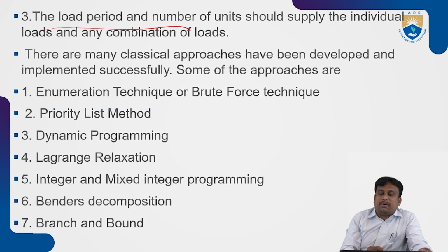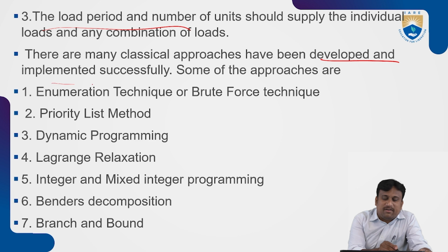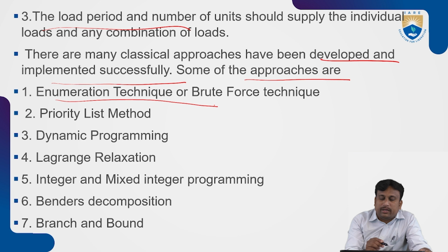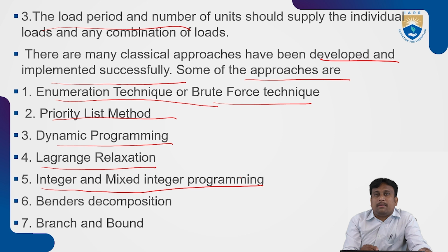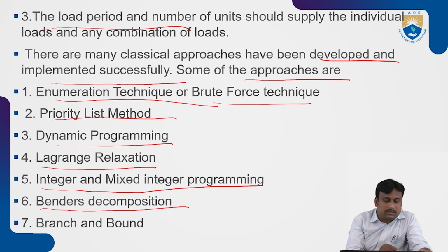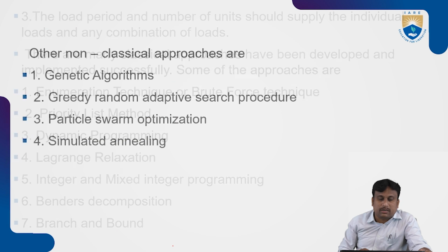So the load period and the number of units supplying the individual loads may be a combination of any loads considered cumulatively. There are many classical approaches which have been developed successfully. They are enumeration or brute force techniques, priority list methods, dynamic programming methods, Lagrange relaxation, integer and mixed integer programming methods, Benders decomposition methods, and branch and bound methods. These are suitable methods for given unit commitment problems.